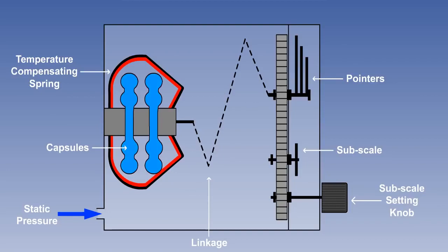Accuracy is also improved by the use of jeweled bearings in the mechanical linkages, which reduces friction. As with the simple altimeter, a temperature compensating device is incorporated, which minimizes the errors caused by expansion and contraction in the linkages. Some sensitive altimeters incorporate vibrators, which help overcome friction and the inertia of the mechanical linkages. This assists in giving a faster response rate to altitude change.